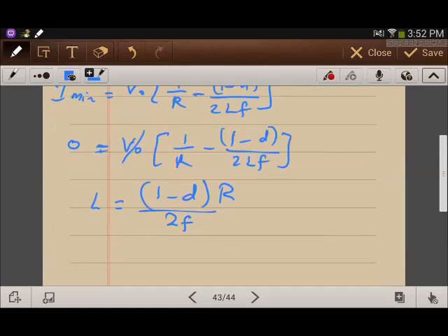So from this equation, increasing the frequency will decrease the value of the inductor being used in the converter. Also, the resistive value of the load will affect the continuity of the current.